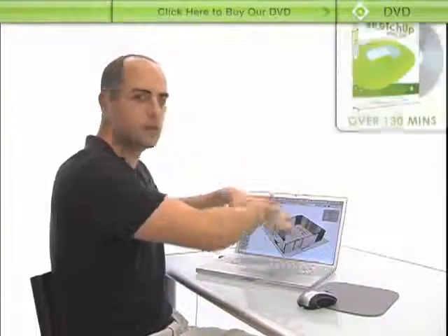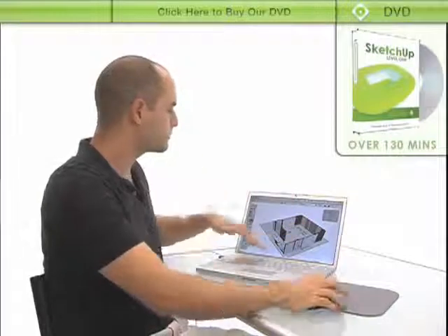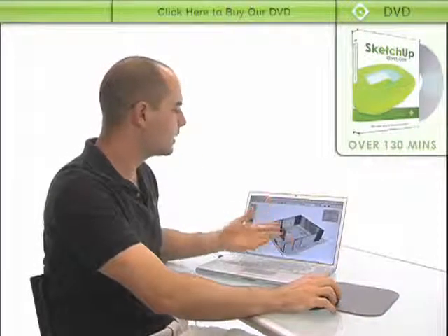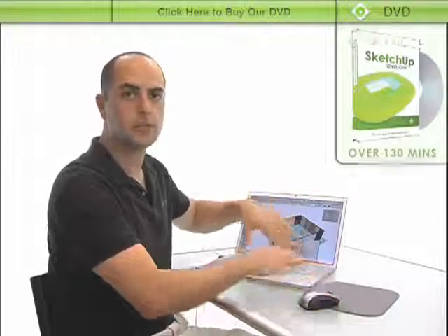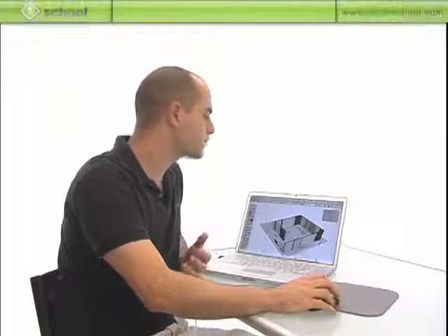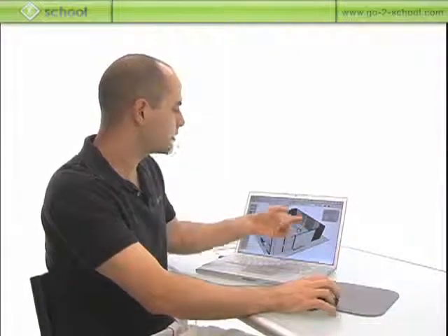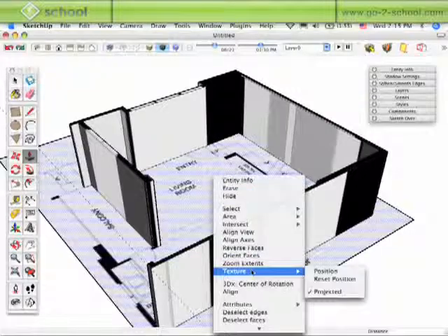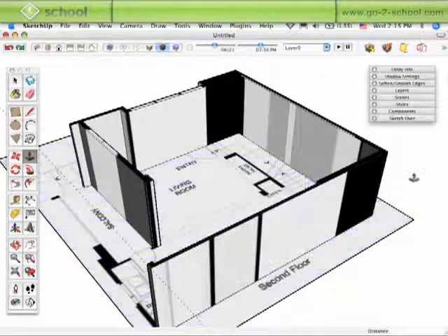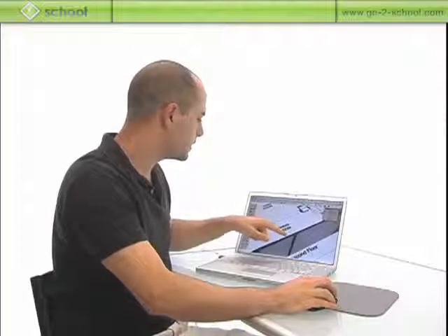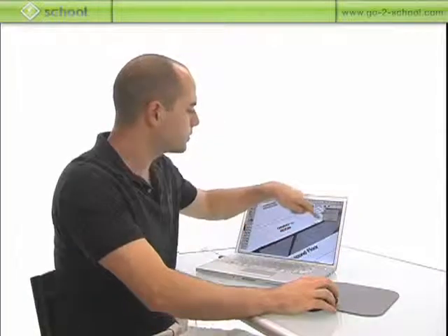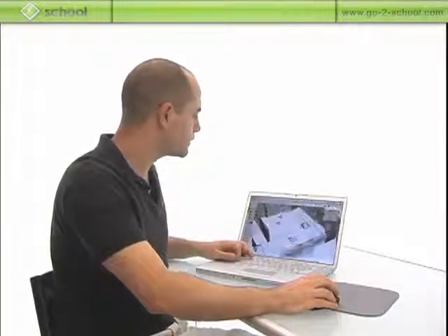On the side surfaces, another interesting thing that you can see is that this image object, when it's exploded, right? Remember back a few steps when we brought that image object into the file, right click on it, you saw the option for explode, and that turned it into a surface with a texture applied to it. The texture that's applied to that surface is a projected texture. So that's why you're seeing this streaky stuff on the side. If I right click and go to texture, you see there's that check mark next to projected. So those streaky lines are SketchUp picking up the pixel color right at the edge of that surface. You can see it over here.